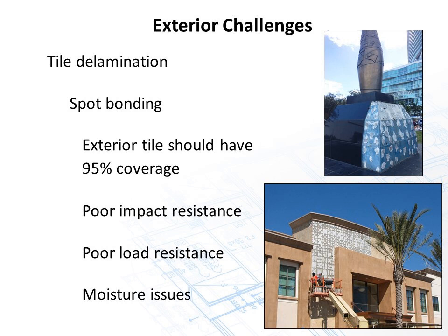Let's talk about spot bonding. The top picture is a memorial. This picture was taken in Miami. Looks like they had great waterproofing on the right there. Unfortunately, it was spot bonded, and this expensive stone was falling off, I think, before they even got the museum open.